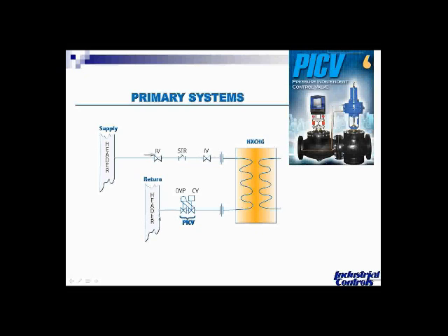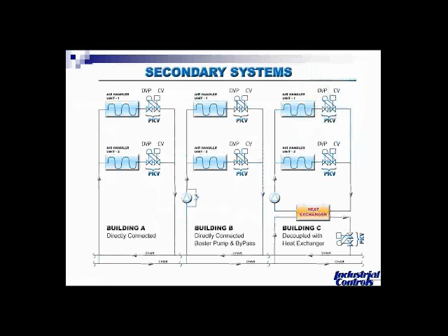That's kind of a simple graphic, but the next slide will be a little more typical if you had a multiple site situation where you have multiple buildings. There's building A, building B, and building C. You have different air handler units in each one, and in this case you would install these on the outlet of the air handling unit of each one of those. And then there's also one coming out of the final heat exchanger that goes back to the return.